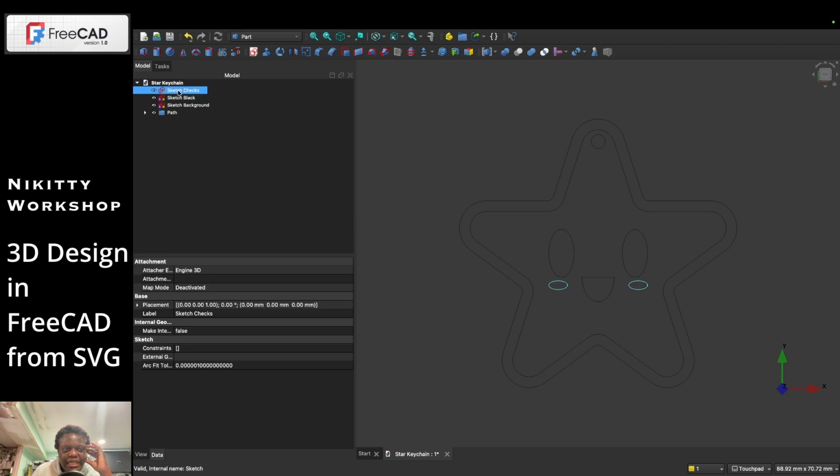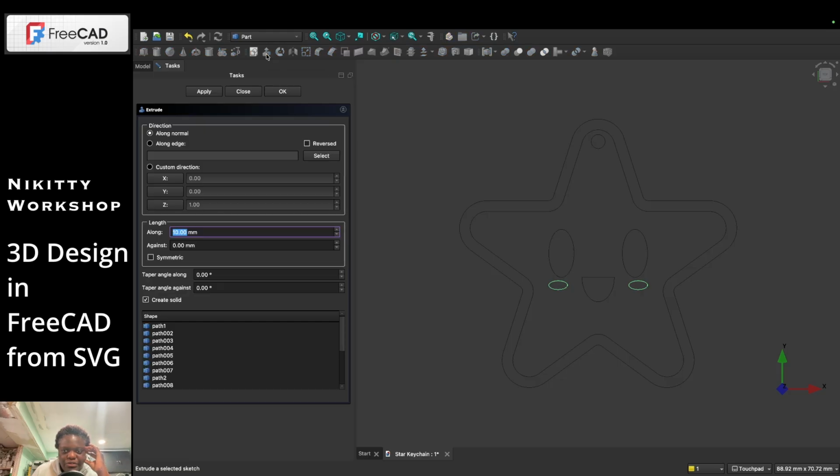So you're going to select the cheeks sketch and you want to hit extrude. I'm thinking of making the keychain about 2 millimeters thick. You could change that when you go into the slicing software, but let's work with 2 millimeters right now. So I hit 2 millimeters. Make sure this, like I mentioned, is positive and not negative. Since it's positive, we don't have to select anything else. We're just going to hit OK.